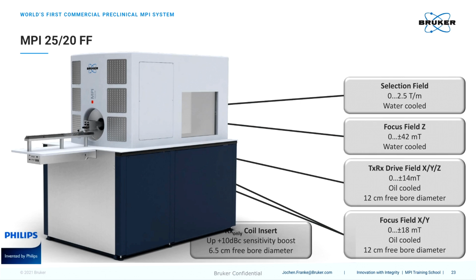Here we have a representation of the signal intensity, or the transfer function, of our built-in transmit-receive coil, and a dedicated receive coil, which can be included in the system case by case. Here we have more than 20 dB difference in signal intensity. So we can tap the MPI signal, which is very tiny, in a much more efficient and more sensitive way.